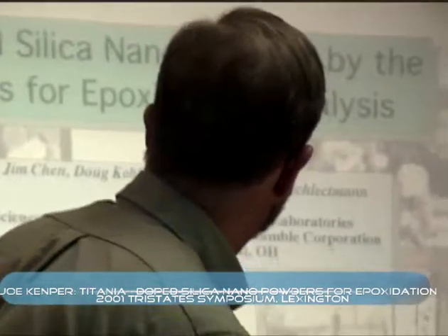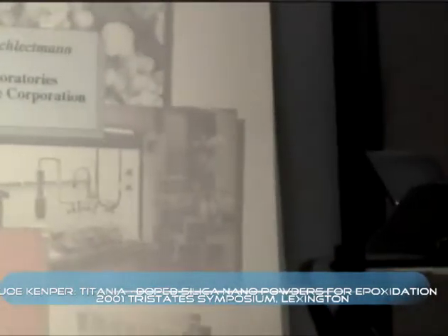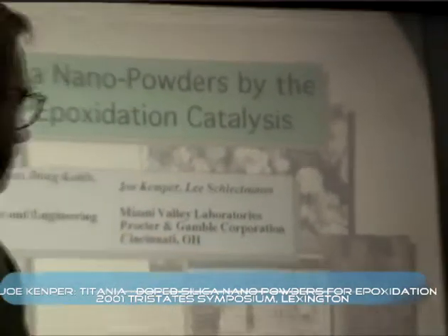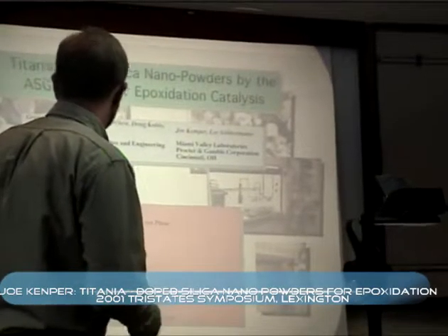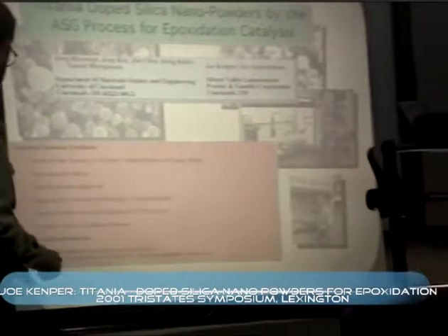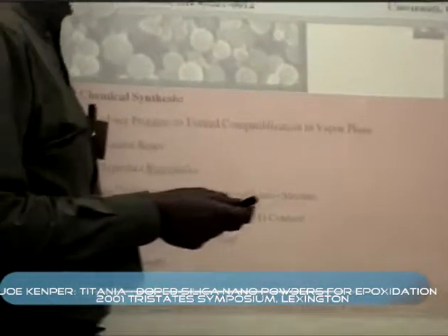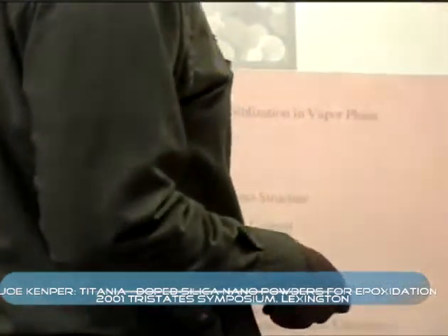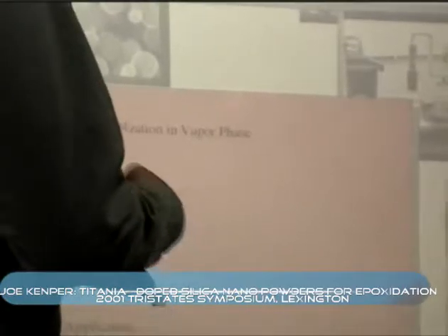Aerosol processes versus solution processes have several advantages. In particular, for the process I'm going to talk about, there's no solvent involved. We're dealing with vapor phase mixing of components and reactions to form metal oxides, mixed oxides in this case.